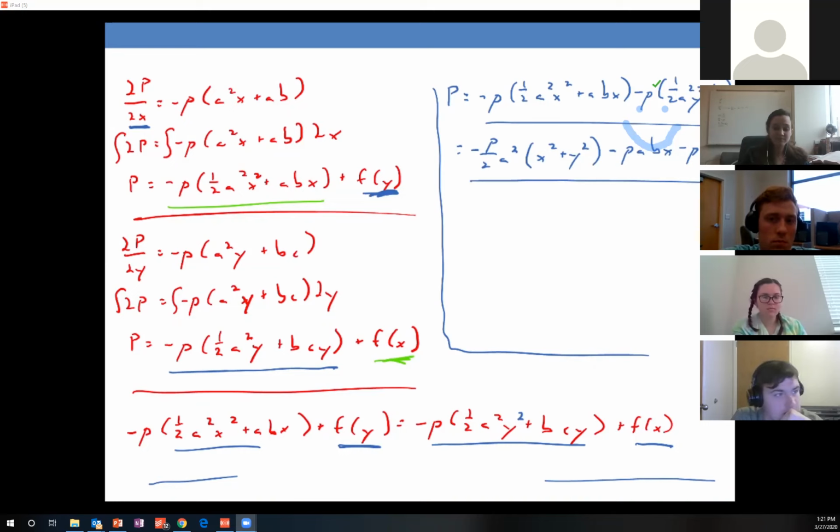Dr. Nickerson, would this be a Eulerian way to look at it because it's about a certain fixed point? It is a Eulerian way to look at it because, if you'll recall, the Eulerian way to look at it is you get just a field. Anytime you find pressure as a function of x and y, you could plot this. You could plot x and y and have some kind of color for pressure, and that would be the pressure field. That is a Eulerian way of looking at it.